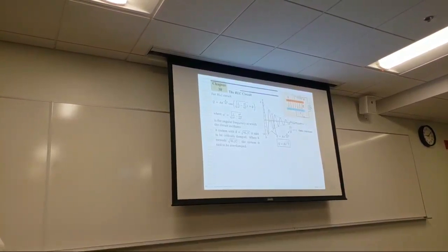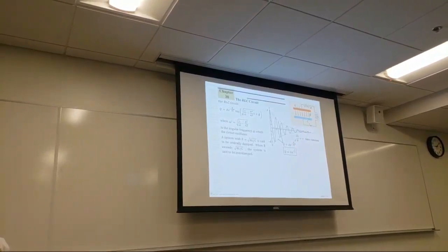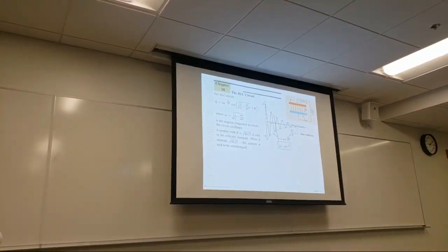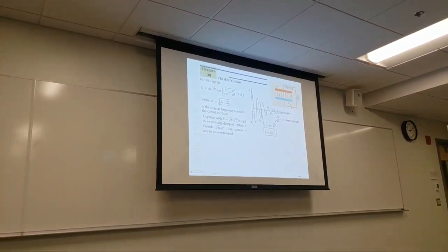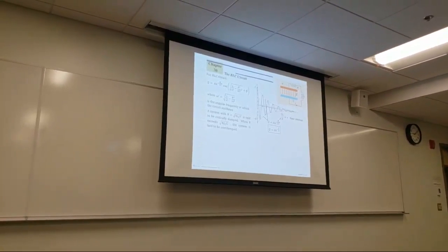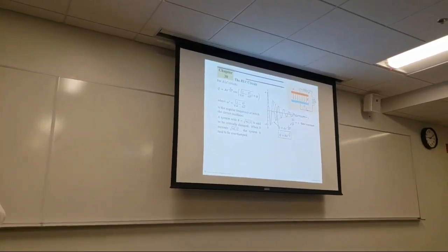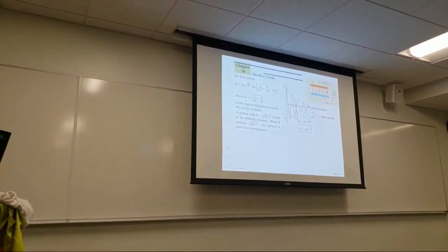And if we did put a resistor in there, what we discussed is that it obviously oscillates, possibly, if the resistance is not too large. When the resistance is too large, then it wants to oscillate, but it doesn't quite make it, and it stops before it even spends all the energy in the first oscillation. That would be an overdamped oscillator.